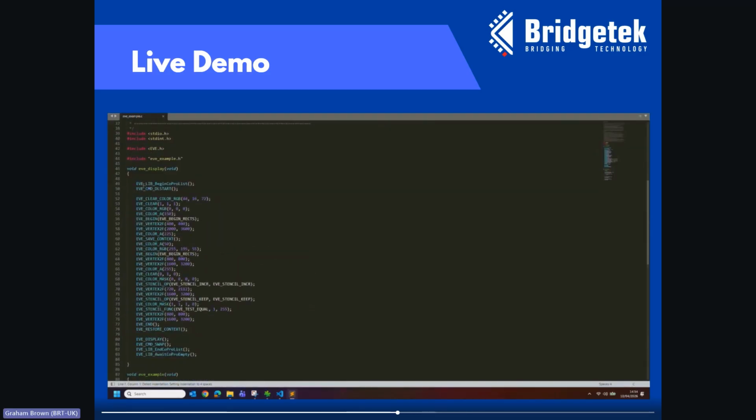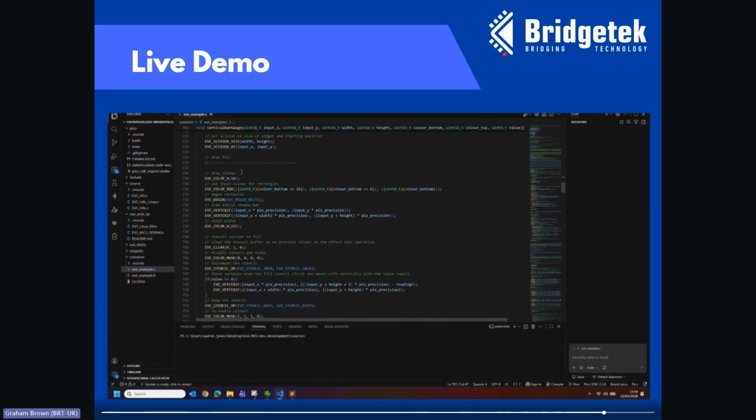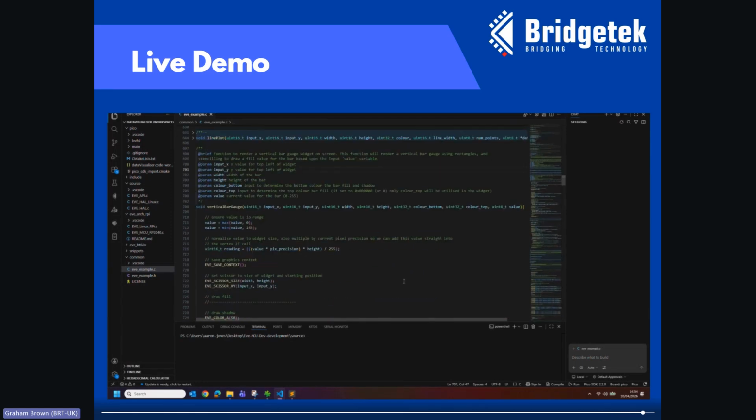As you can see here, there's a main example file that includes all of the commands that we've prototyped in Eve Screen Editor. Now, if we want to take the bar gauge and create a standalone widget out of this, these are the commands that are relevant, as the other commands were for the background of the bar gauge and the main screen. So we can take these commands and place them into a function in our main application, as we have done here, such as the vertical bar gauge. And you can see we have parameterized this, so we can place this on the screen where desired with input X and Y's, as well as a height and width, and then the value we wish to display on the bar gauge, including also colors if we want to recolor the item.